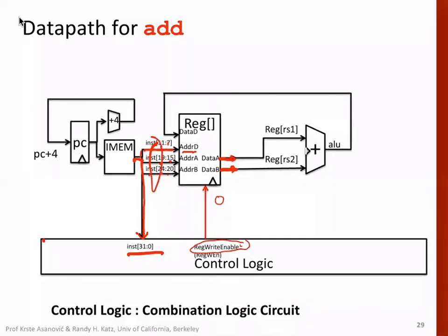Next thing is that these will be added, and then output will go to this register here. And when the value is available in the last phase, this read write signal becomes 1, and so the corresponding addition value, whatever value is available, will go inside register RD.